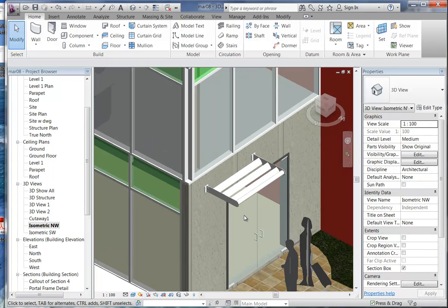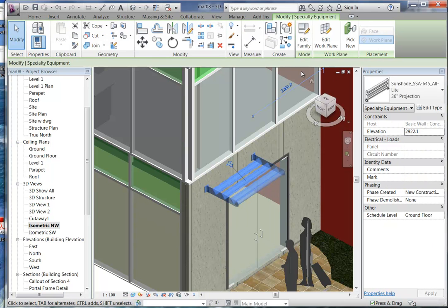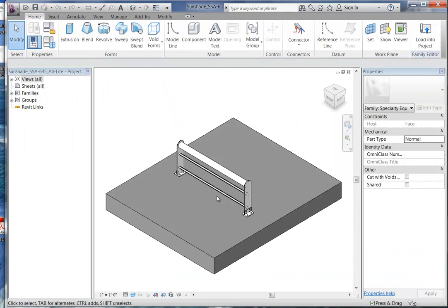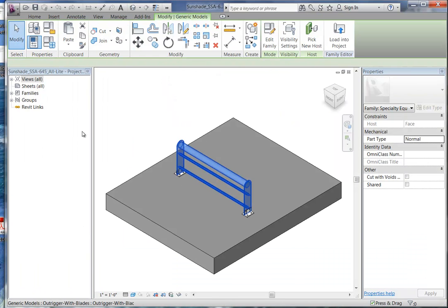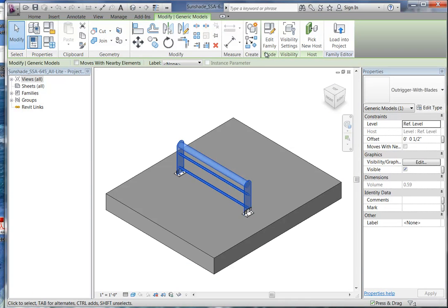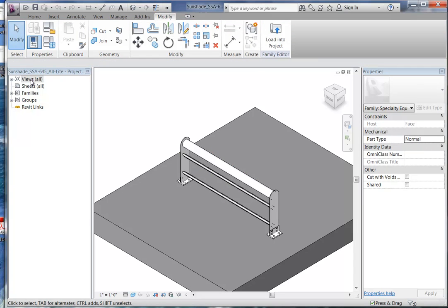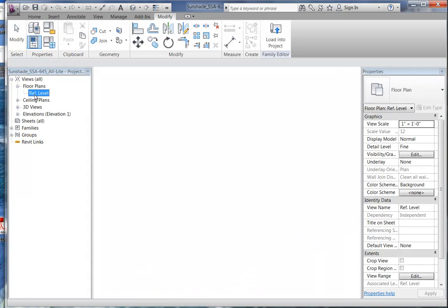So that's why Revit is good, because you may not be able to use the family as is, and same with Autodesk Seek, but it'll be close to what you're after, and then you can just modify it. So here that's too narrow, but I can just go to Edit Family, and here it's got a nested family, so I've got to select that object and Edit Family again, but I'd be surprised if it doesn't have a parameter for the width.